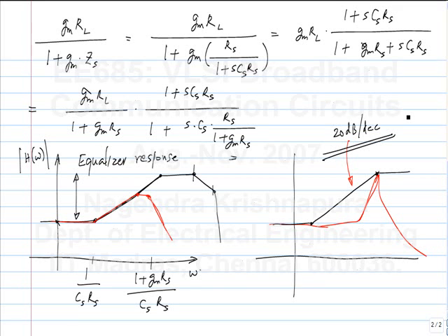So something like this does a better job than a second order filter generally. But still, you have very limited degrees of freedom. I mean, you can only choose at what frequency you place the zero, so that it starts boosting up the frequencies. Whereas theoretically, if you have an FIR filter with a large number of taps, you can adjust the shape very finely. Right? You can get a response that is perhaps like this. Of course, that needs more taps, but you can get it easily.